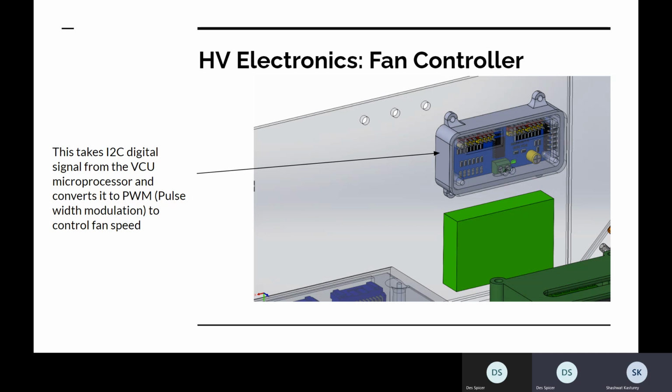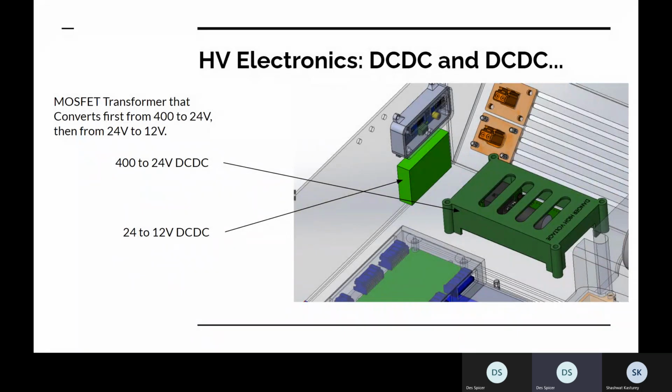The problem with the one that you're looking at is that the frequency rate of the PWM controller on it is too slow, so it won't control the motors inside of the fans fast enough. Knowing that, I decided to make a new one.